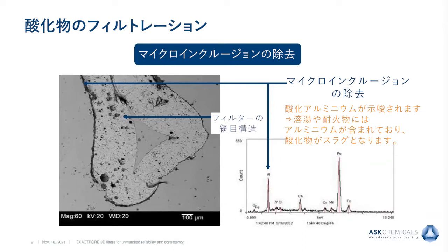The refractory that's used in steel foundry processes is high in alumina. The furnaces and ladles are made of alumina refractory, and these materials can be easily eroded or spalled during the process. Additionally, aluminum is used to deoxidize steel. The aluminum reacts with the oxygen in the steel metal, creating residual alumina oxide. These aluminum materials need to be filtered with the reticulate foam.